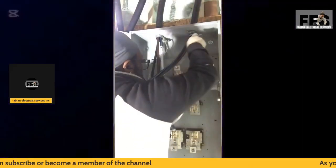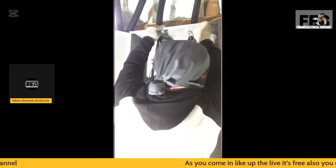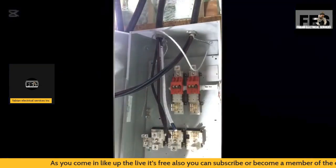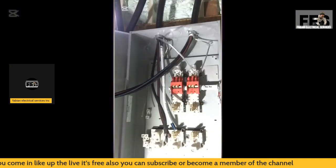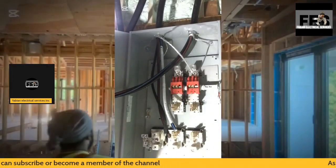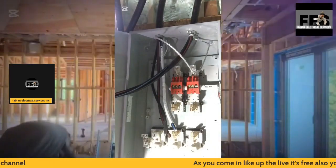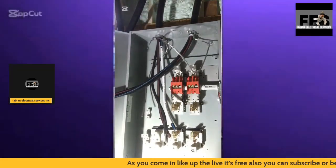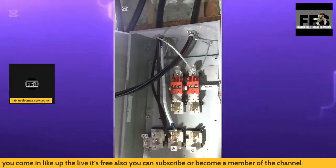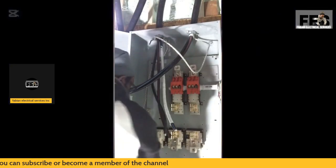Also, you're going to see I have my phasing tape on my cable. The reason is this cable does not come with an identified neutral, and in the code book it simply states that your incoming neutral has to be identified. There is an electrical code rule that states that for a particular size of cable we must identify it. So this is what I am doing here, identifying my conductors with the white tape that is being used.